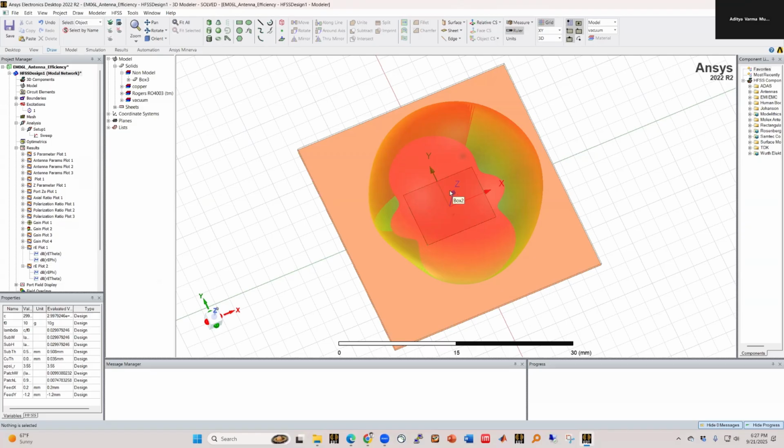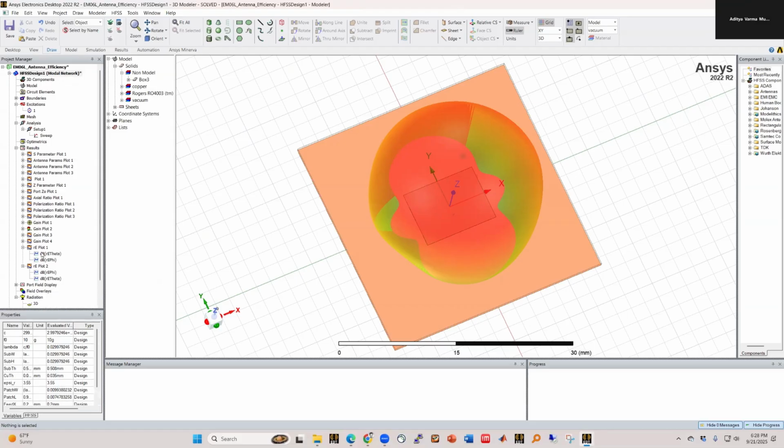So the way HFSS resolves that is that it sees you're plotting along the YZ plane, so at theta equal to 0, it sets E theta as Ey. And along the XZ plane, it sets E phi equal to Ey. So at that point, it's not really well defined.